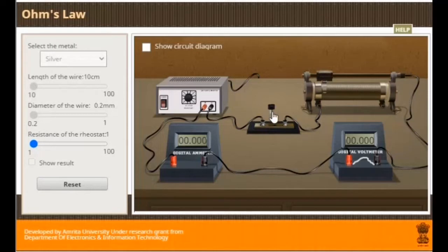And then close the switch and read the voltage and current on the meters and record the data. But the data in this simulation is not accurate because it is only an example. Then after it is done, change the position of the rheostat from 2 to 8. You need to change this, okay? And collect the data for each reading of different position of rheostat. Next, compare and analyze the data collected into a table and graph.